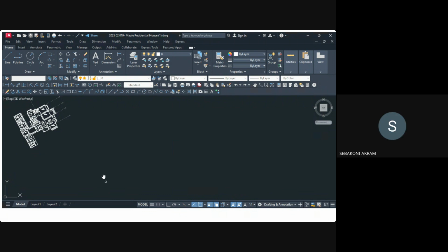So I come here, name. When I type that name, it brings me all the layers that are existing. Besides the active one, you see it doesn't bring the layer 0, because layer 0 is the active one here, as you see. So these other layers are brought forward. So you select these layers, because I'm going to delete them.